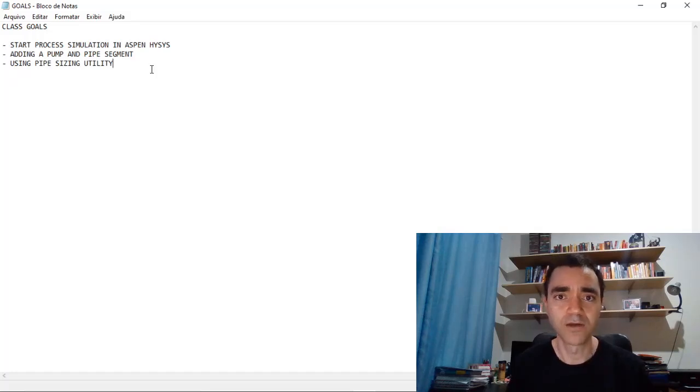Now you learned how to start your process simulation in Aspen Hysys. Moreover, you found out how to add a pump to your process simulation and also a pipe segment. And as a bonus, you learned how to add and set the adjust object. And it is an intermediate to advanced technique to converge your process simulation.